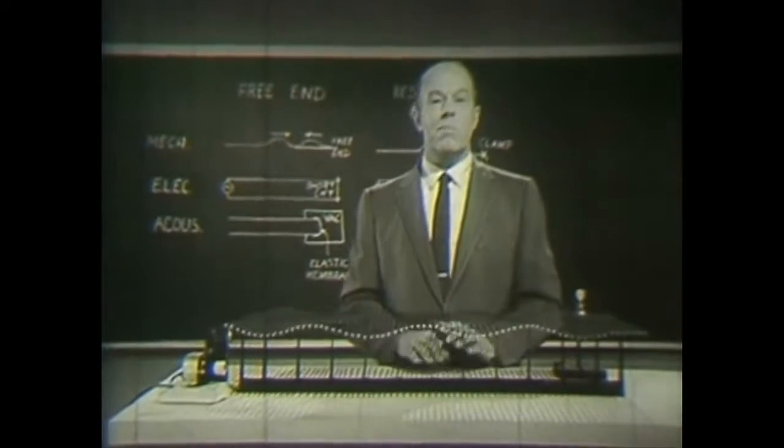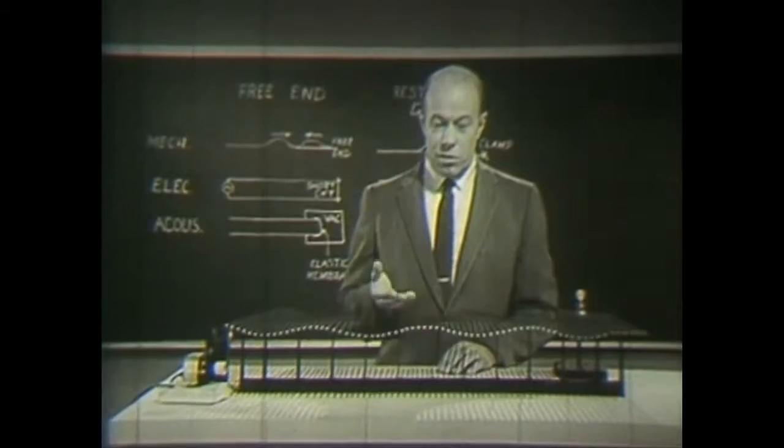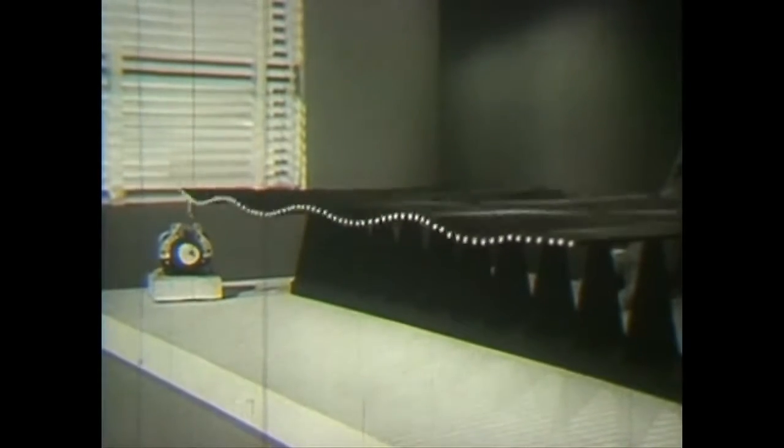The system thereupon becomes resonant, and the amplitude builds up to the noticeably larger value that you see here. Under these conditions, the new energy which is being fed into the system at each cycle is exactly equal to the energy which is being dissipated per cycle through friction at this new amplitude.